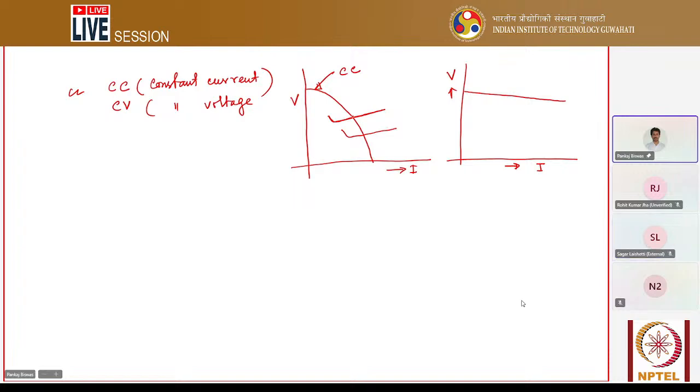So you see this arc characteristic curve, this is called what? Arc characteristic curve, that I am writing. Arc characteristic curve, and these are power source characteristic curves. Where it is crossing, that point is called the working point, PW. PW means working point. Why is it the working point? Because whatever current and voltage you get, that is your welding current and that is your welding voltage. This is well known to you, correct?